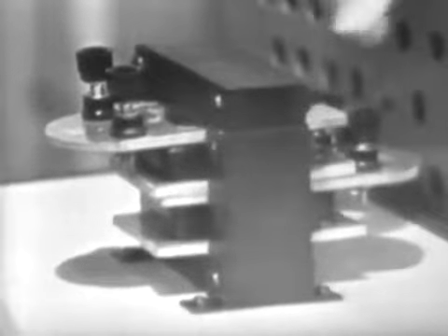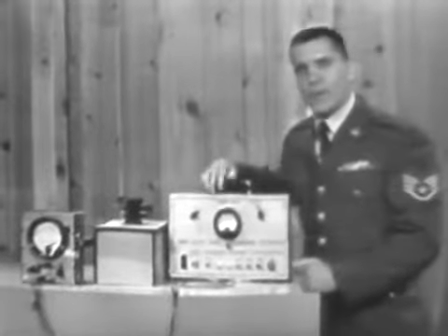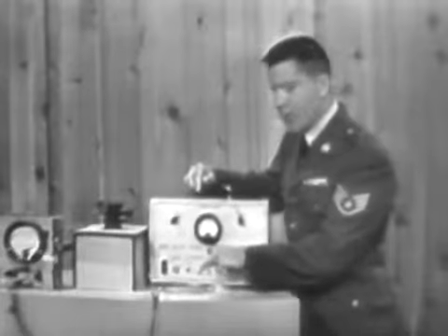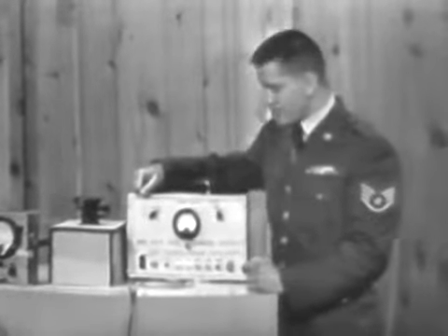Now, over here, I have a transformer demonstrator. As you can see, it's composed of an iron core and two windings. One of these windings will serve as the primary of the transformer, while the other winding will serve as the secondary. In the demonstration, we'll be using the bottom winding here as the primary. Now, here I have a power supply, and from these two terminals on the power supply, we can obtain 6.3 volts AC. I'm going to apply that 6.3 volts to the primary of this transformer, and then we'll use our PSM6 and measure the voltage available at the secondary. Let's go ahead then and apply the 6.3 volts to the primary of the transformer, which, as I've already mentioned, is the bottom winding here.